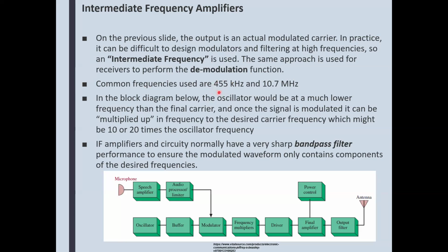So for AM, 455 kilohertz, and if you look at the scale of the AM clock radio that we have in the classroom, or if you even Google the AM scale, 455 is well below that scale. And that's where we want to have it, so it's not interfering with all the circuitry.